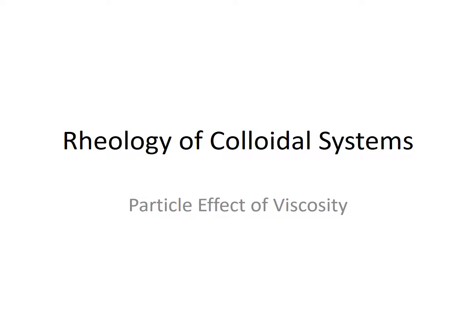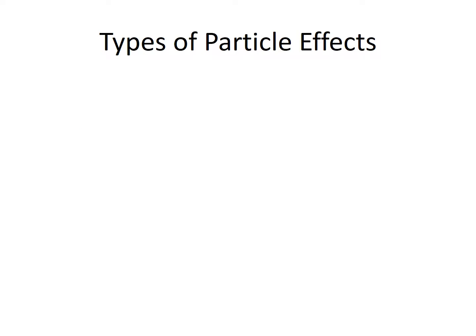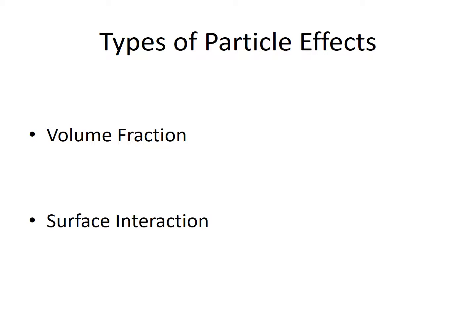Today, we will be discussing the rheology of colloids, specifically how the colloidal particles affect the viscosity of the colloid. There are two main factors of the particles that can affect viscosity. First is the volume fraction of the suspended particles, and second is the surface interactions between those particles. We will first start with the volume fraction.